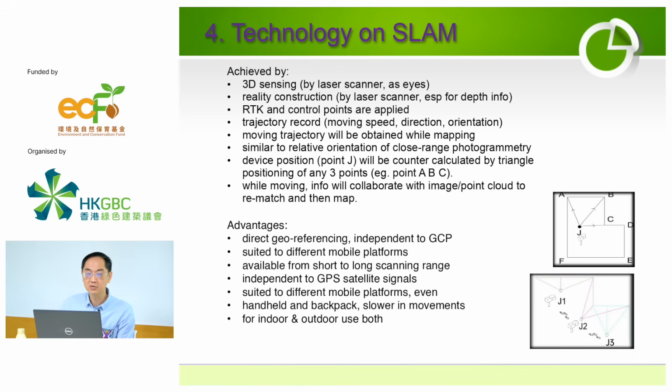While moving, the information will collaborate with the image and point cloud to rematch and then map. The software will continuously calculate to redefine or check the real position. The advantage is that it will give us direct georeferencing. It is independent of ground control points.